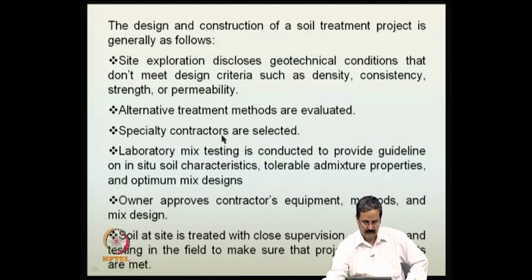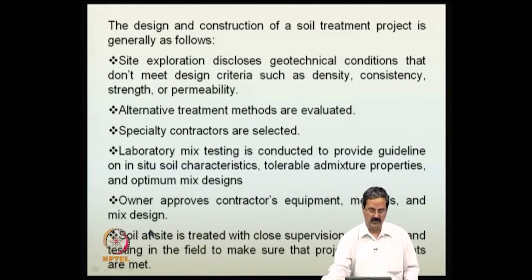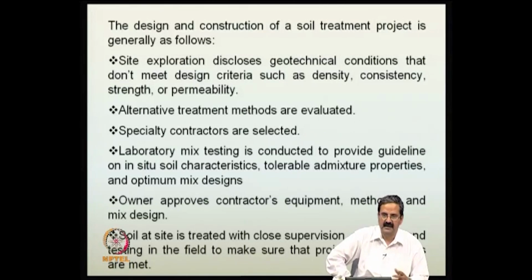Now, what should be done is that it is always advisable to conduct some sort of laboratory mix testing. Suppose you have Cochin marine soil, take it and try to find out the in situ properties, then find out how the properties are improved with the addition of cement or lime or admixture in some combinations, and so you come out with tolerable admixture properties and optimum mix designs. So, come out with what the mix requirements are.